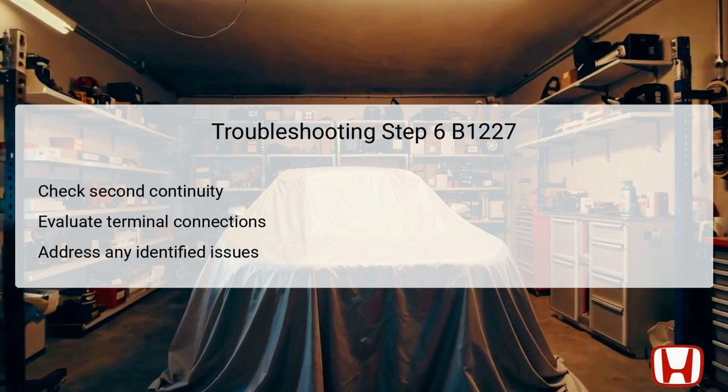If this test confirms continuity, the next task is to check for loose wires or poor connections at both climate control unit connectors A28P, B12P, and the outside air temperature sensor 2P connector. Confirming solid connections at these junctures is vital for reliable climate control operation, as any loose connections can lead to erroneous temperature signals. Should issues still persist despite these checks, substituting a known good climate control unit may be necessary to identify if the original unit is faulty.